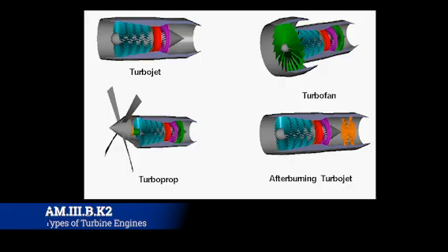So then people are like, well, okay, now what do we do? If we wanted to fly up to 40,000 feet, what else can we do? And so you replace the turboprop with a fan up front on a fan cowl, and all of a sudden things start to become even more economical at altitude, and you still get the performance of the jet. Now, it doesn't go quite as fast as a turbojet, but it's not quite as economical as a turboprop. It's kind of this middle ground where you get the turbofan.